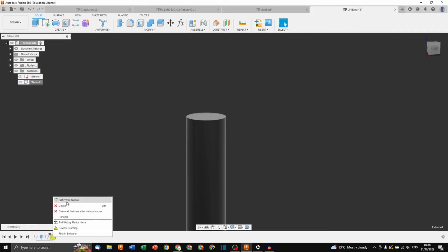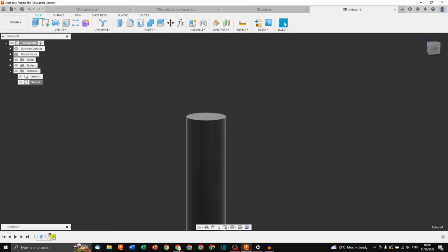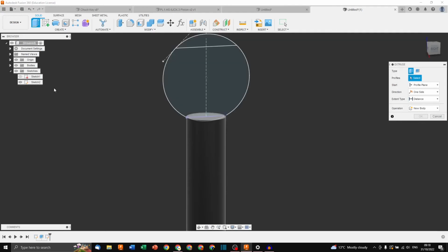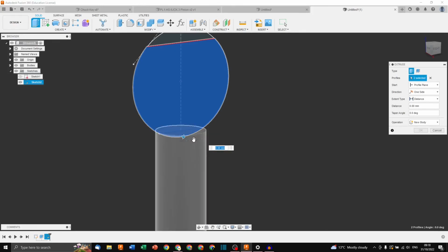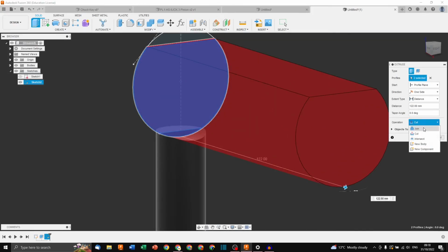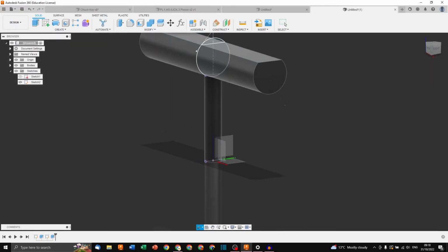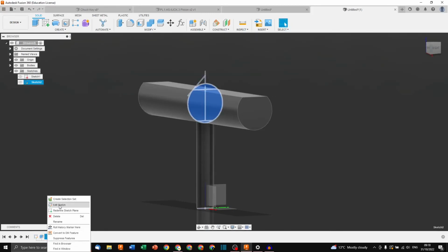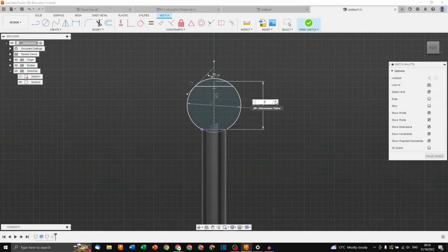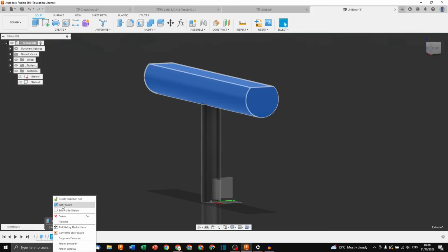it'll be orange. Let's edit the profile. Nope. Let's edit this. Let's just delete it actually, and let's make a new one. Let's unhide the sketch and let's pull this and this a good distance as a join and a symmetrical. We'll see this in the next video once again. And now you created a much bigger handle. I can hide the sketch, and I can now edit the sketch diameter right here by changing this to 30. And you can see it works perfectly well and nothing breaks.